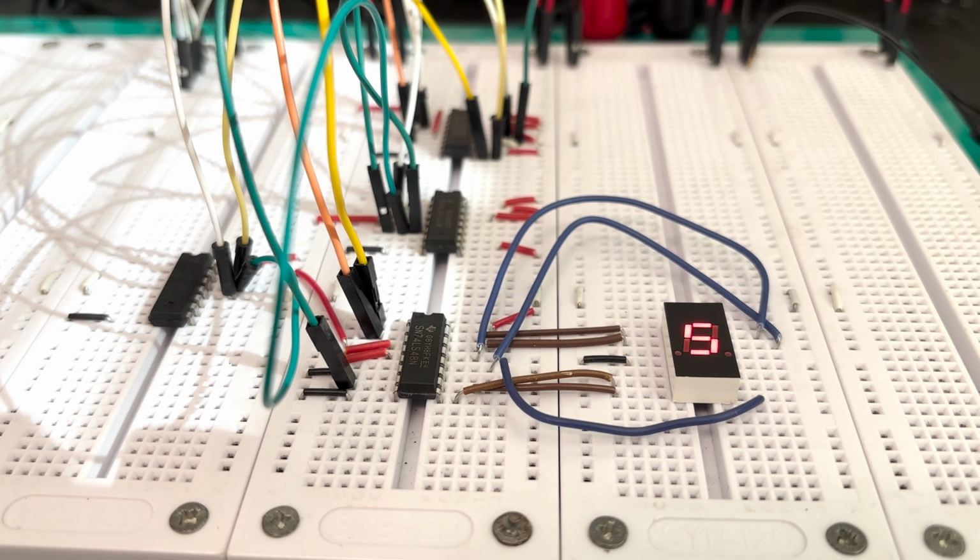After this circuit is powered up, each time the clock ticks, the counter will increment as dictated by our expressions, which should hopefully align with our state diagram. If we want to connect the outputs to a BCD to 7-segment decoder, we can watch the counter count through its sequence and confirm that it works.